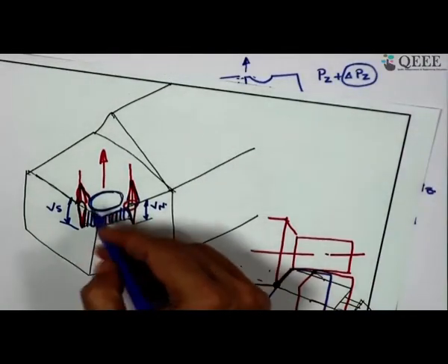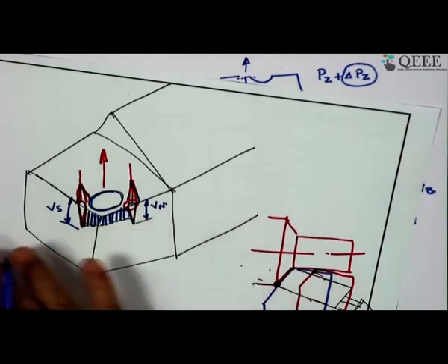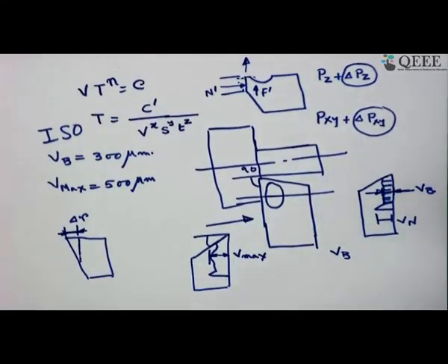That means, at the tip of the tool, the wear directly affects the accuracy on the job, which affects the dimension, depth of cut change. In certain cases, of course, we have tool wear compensation for advancing the tool, but that also has certain limit.